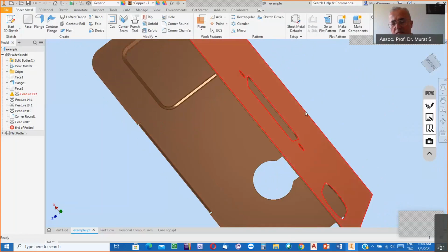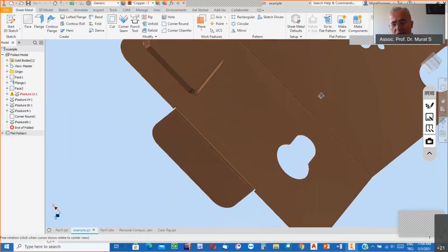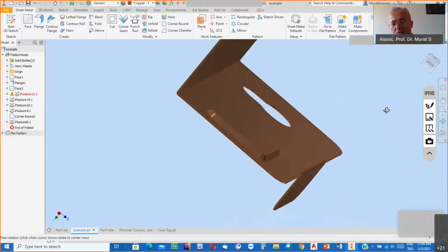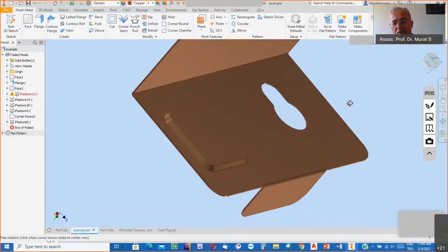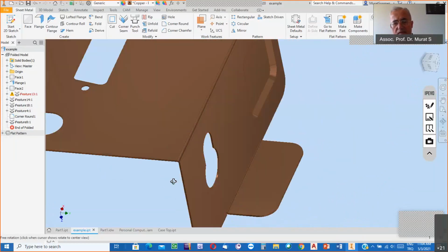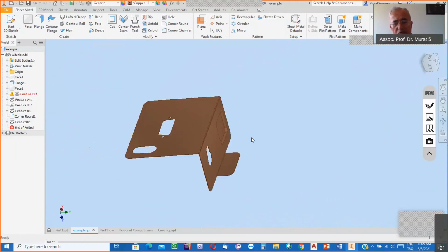Without such reliefs, if you attempt to bend the sheet metal, of course not in a virtual environment but in a real environment, real life, then sure, at the beginning and at the end of such a bent part, there will be extremely large stress values, and the atomic bonding forces most probably will not be sufficient to balance the applied forces. So there will be a failure here and also there. But using the reliefs, creating such special cuttings, we prevent undesirable excessive stress concentrations.